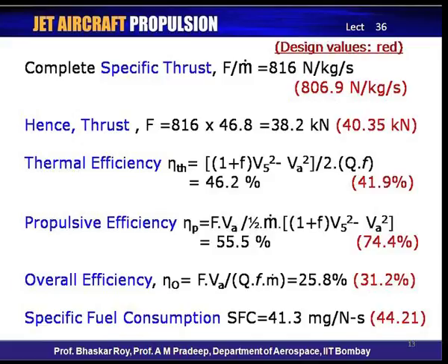point value, where we get 44.21, which means that the specific fuel consumption at this operating point is actually slightly less than the specific fuel consumption of the design point, which was our flight Mach number at altitude of 12 kilometers at Mach 2.